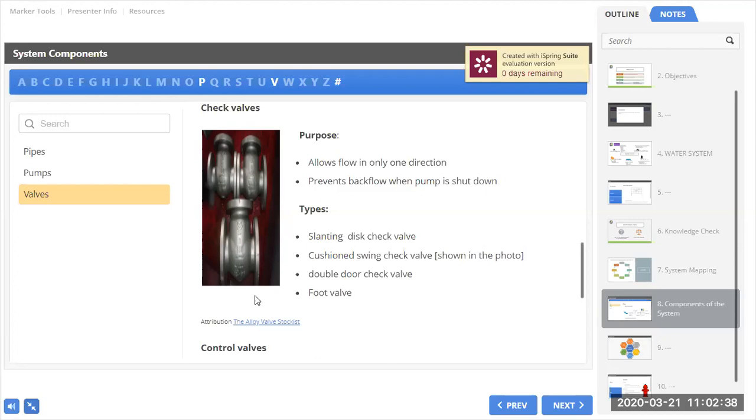The third one is to pressurize the water system. We want to maintain positive pressure, so we have positive pressure from elevated tanks. These are tanks that we use specifically for maintaining pressure. Some of these tanks might not store as much water as other tanks, but that is because they are mainly there to provide an injection of pressure into the distribution